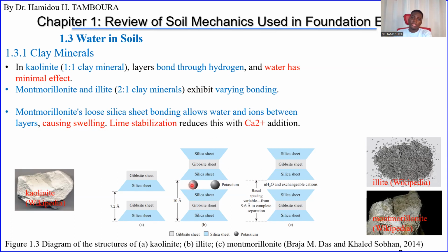Sometimes when you have this kind of clay at your construction site, people use lime stabilization. By adding the lime, we are adding Ca2+, and this addition will reduce the effect of water on this clay.